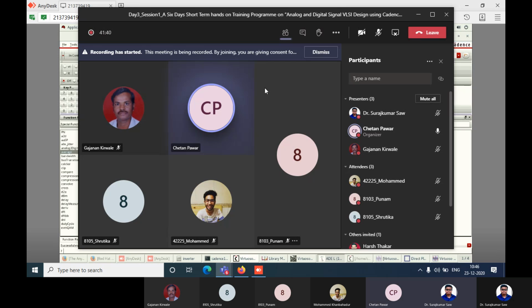Yes, power. No, don't select instant power, total power. Select total power, add to output, then plot. Click on plot. Okay, take the average of that. Now you click on that signal and send to calculator, okay? Shrutika.